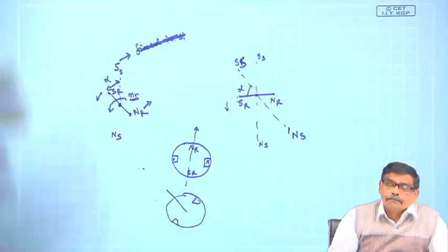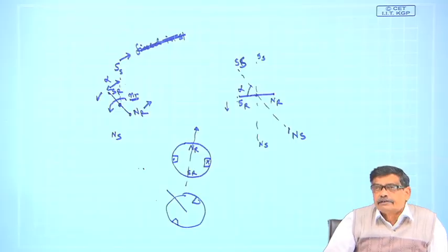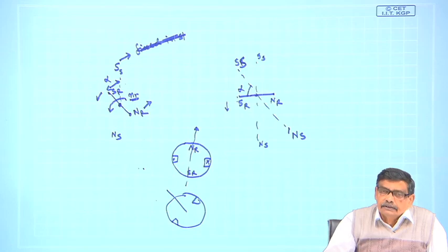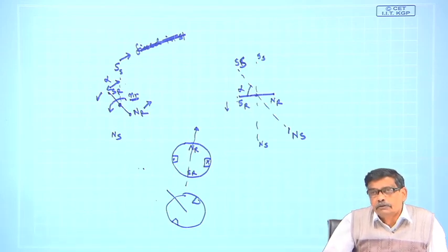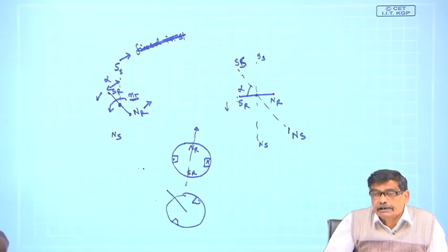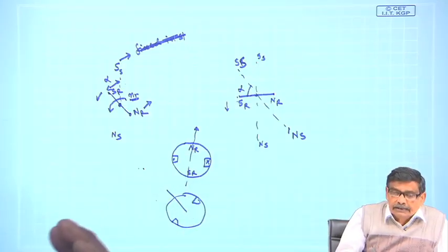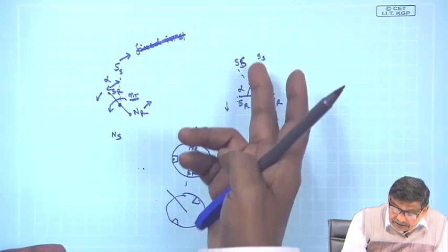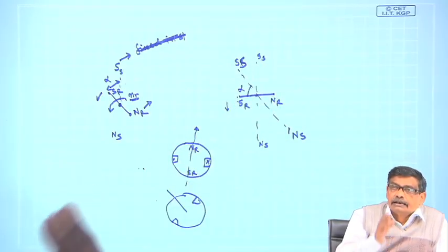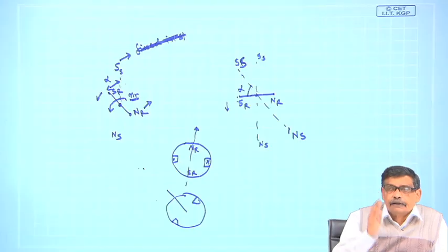to produce sustained electromagnetic torque, you must see that the stator field and rotor field are moving at the same speed with respect to a stationary observer, such that the relative speed between them is 0, no matter in which position the rotor is. The angle between this stator and rotor field must remain constant.